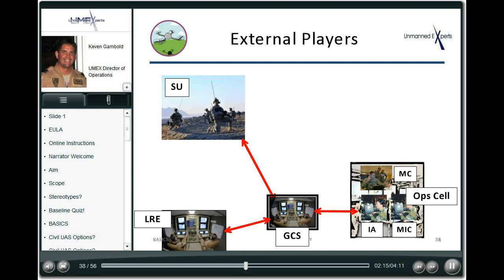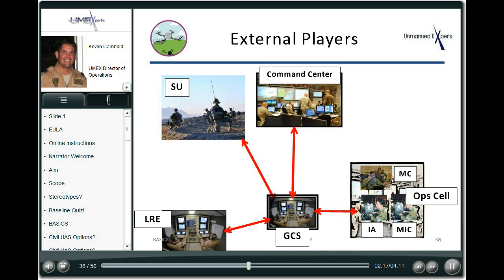But it doesn't stop there. So we have a number of external agencies that are both monitoring the feed from the UAV, normally through that level 1 LOI, but they're down the PED, the processing, exploitation, dissemination chain that we saw earlier on. And they have direct inputs, normally through the mission commander, to the GCS to retask the aircraft, to send it to other subordinate units, to send it home early, as you see fit. But you do get an enormous amount of interplay there.